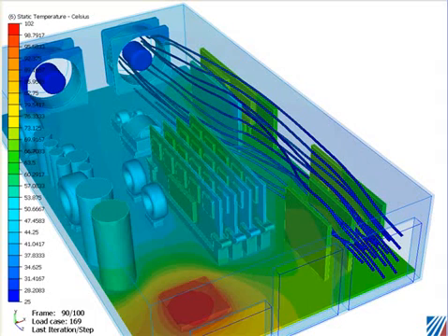A simple and inexpensive solution would be to include a flow diverter downstream of the front boards and include an additional ambient intake for the downstream components.